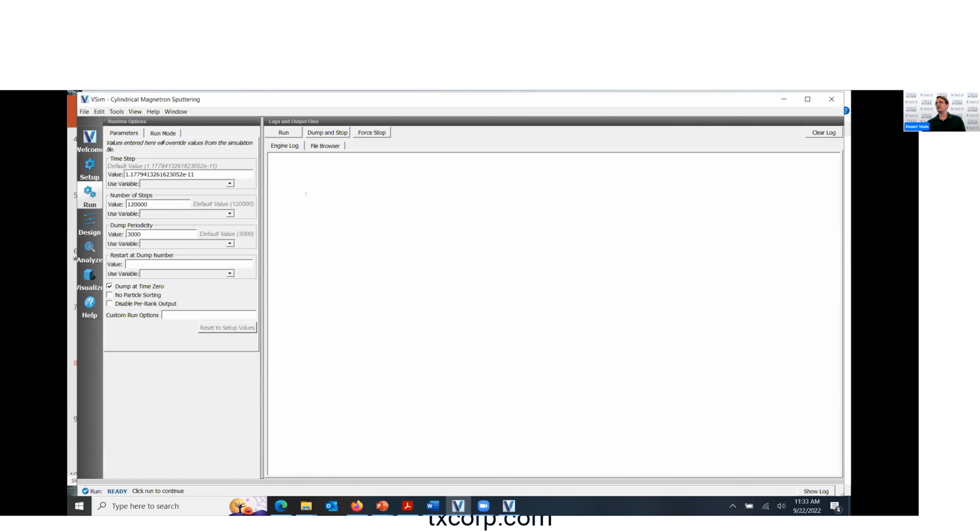This is a pretty computationally intensive problem, so the more cores you can throw at this, the better, limited of course by MPI decomposition. Probably 32 cores would be good if you wanted to do it in a few hours. I ran this also on 8 cores, and it probably took about 8 to 10 hours to run. On 16 cores, about half that.